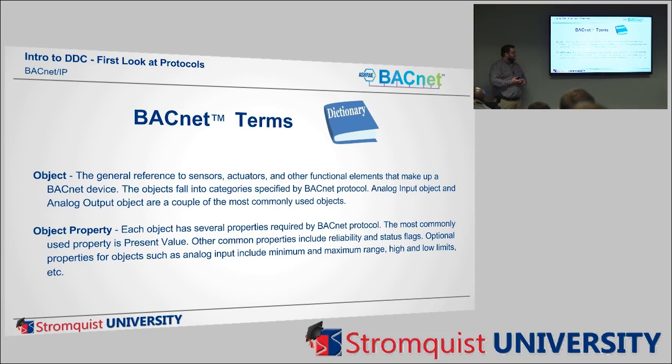But it also has some that are, bad sensor, maybe something's out of, unoperational, and min and max ranges that are valid for that sensor. So if you have a space temperature sensor and it's reading 0 degrees and your minimum is 30 degrees for that particular sensor, it'll generate an alarm saying the sensor's bad.